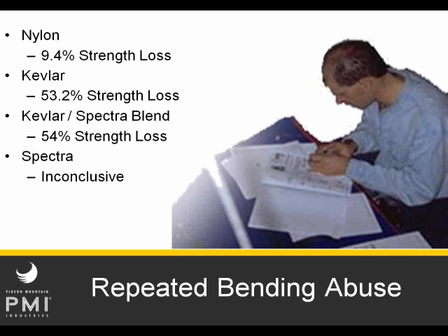So as we can see, they're not very predictable, and some of the newer, fancier fibers that have very, very high strength actually have some real significant problems when it comes to bending or even knot tying. As with some of the other things we've mentioned today, there's not presently a test for this in the Cordage Institute. There's not one in National Fire Protection Association. There's not one in ANSI. There's not even one in the Euronorm standards. This is just something you need to be aware of, and if necessary, run your own backyard tests to ensure that you're going to be safe in the systems that you use.